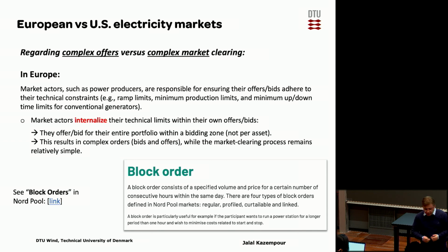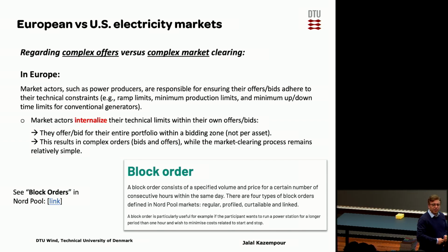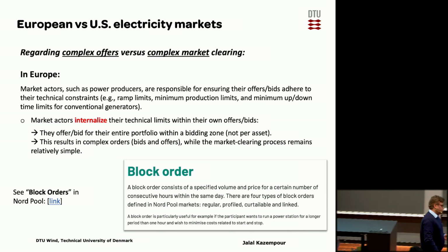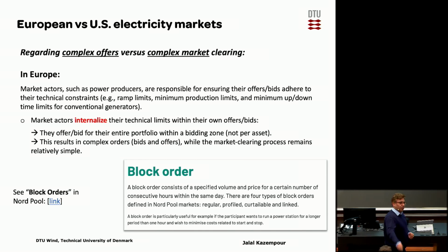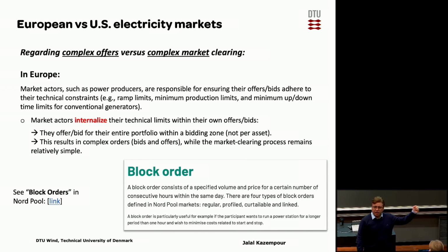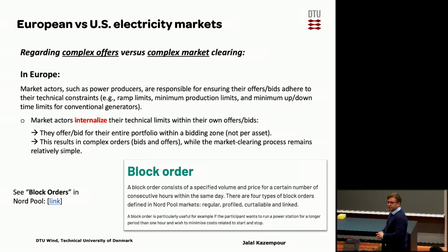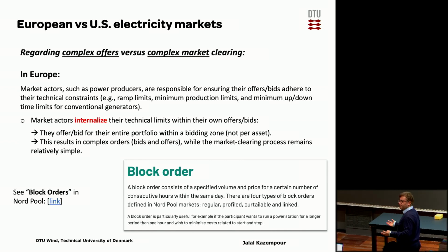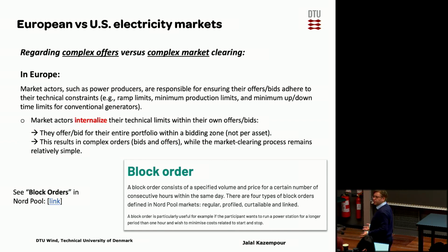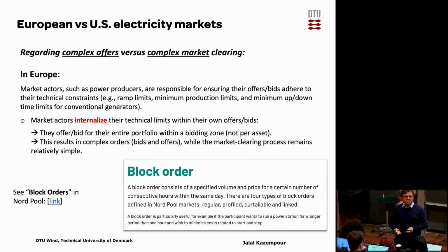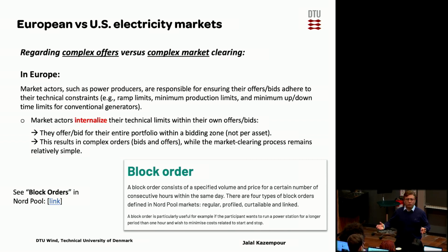For example, if now you are producing 10 megawatts, can you increase it tenfold to 100 megawatts by the next hour? No, there are thermal and thermodynamic limitations. So conventional generators usually have technical constraints like ramp rates, minimum uptime, and minimum downtime. Have you heard of these things? For example, if you are on, you should stay on for at least 5 hours.